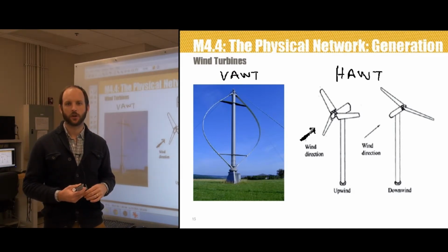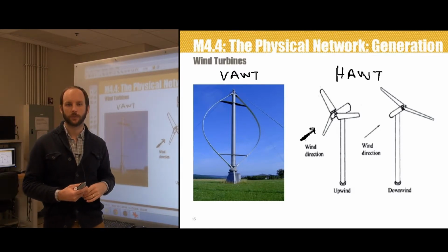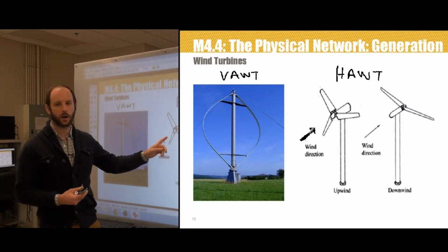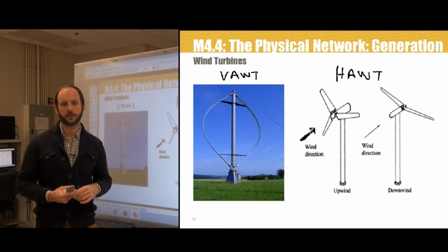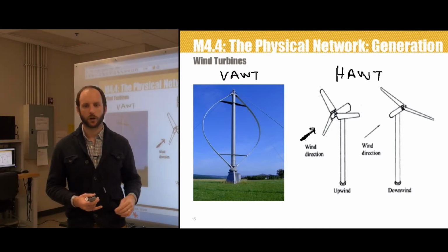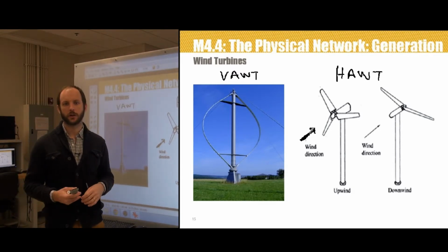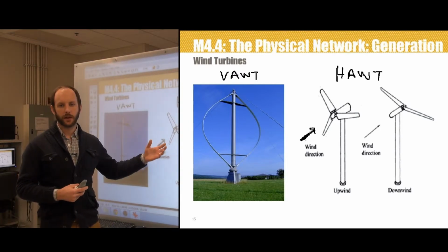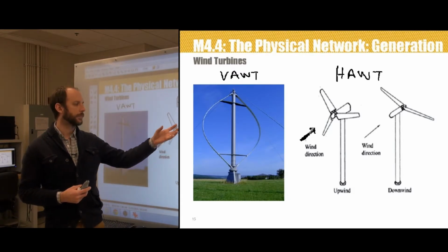Multi-bladed designs present a large area of rotor that's facing into the wind, enabling both high torque and low speed operation. As the RPM of the turbines increases, the turbulence caused by one blade will start to affect the efficiency of the following blades. Therefore, with fewer blades, the turbine can spin faster before the interference from turbulence becomes excessive. Faster spinning blades result in a generator that can be physically smaller in size. So with many blades, I can have low speed, high torque, but I need a big generator.